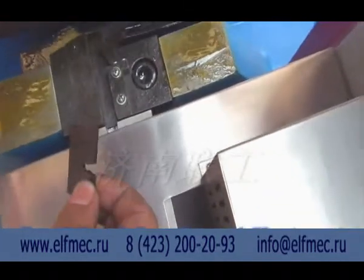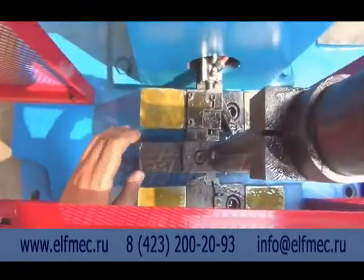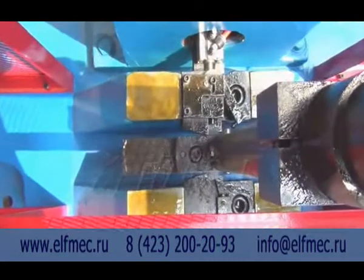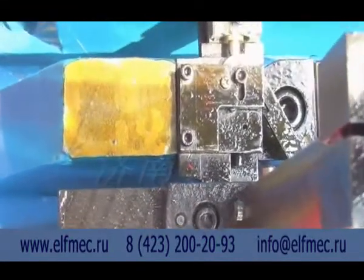Small pendulum span adjustment. Place the span alignment plate on the impact jaw spot. The gap direction overlaps with the pendulum blade. Then push the pendulum lightly to the gap of the span alignment plate.